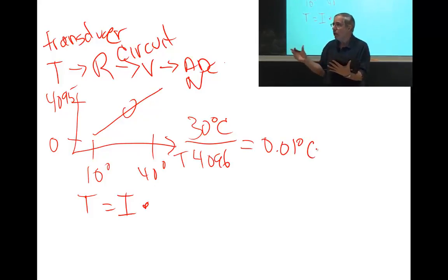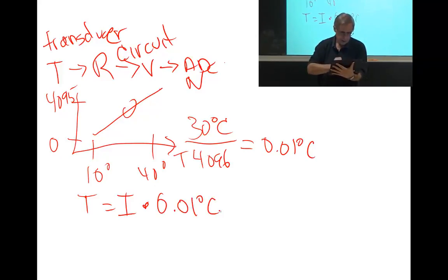And this is a thermometer. People don't like binary fixed point. Their eyes like decimal fixed point. So what do I design the fixed point number system as? What delta should I choose? 0.01, yeah. So choose decimal, 0.01 C. Notice the delta has units. The other one had volts. This one has degrees centigrade. So that's going to be my defining part of the decimal fixed point value.